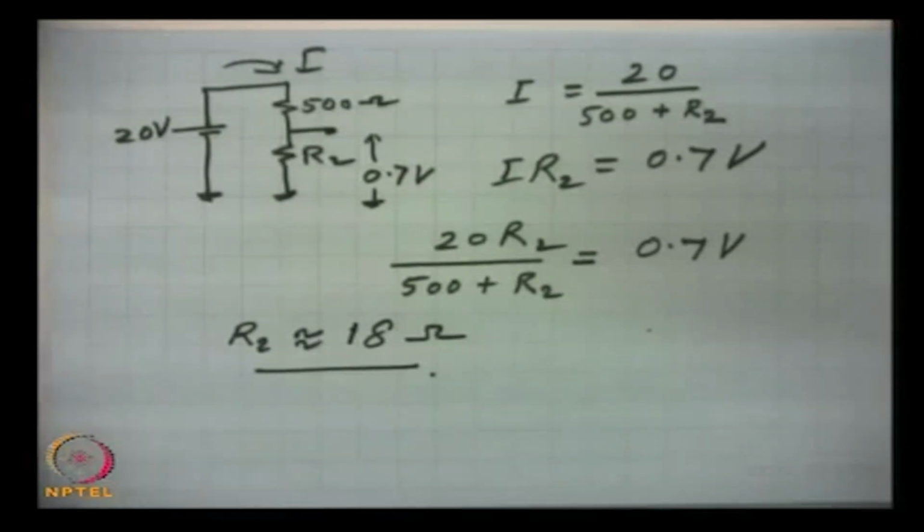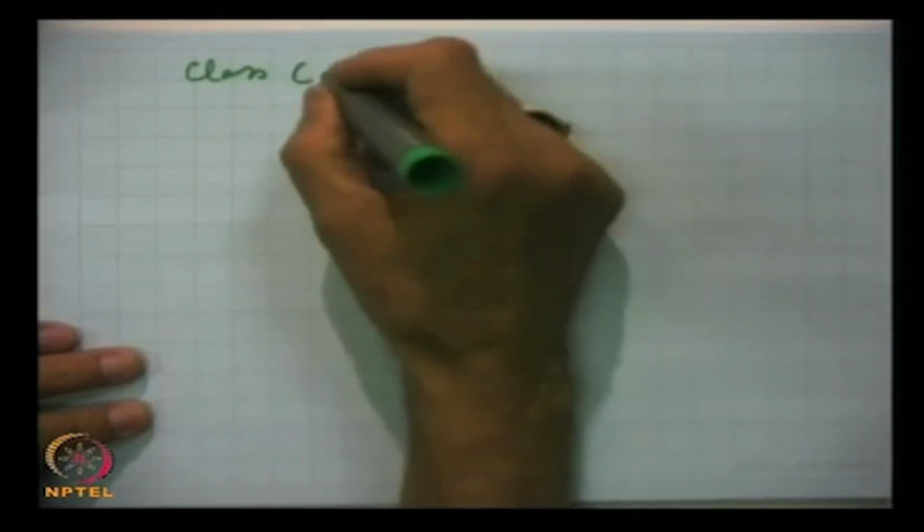I wanted to illustrate two points. One is that half circuit is sufficient for the analysis of push-pull amplifiers. No matter how complicated the analysis is, it is always done with half circuit, and the second point was that simple methods are there to calculate these parameters. The next power amplifier after A, B and AB is the class C power amplifier.